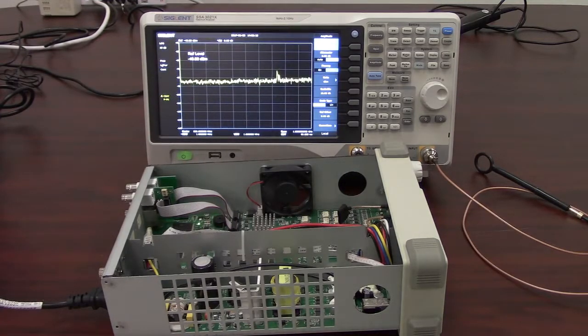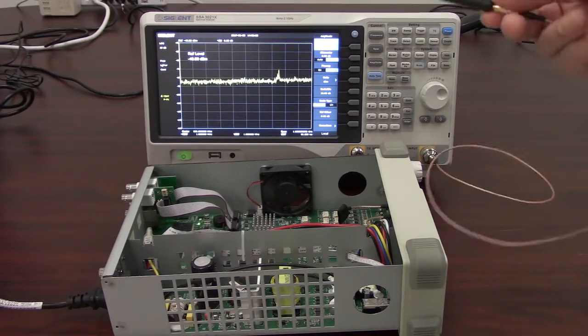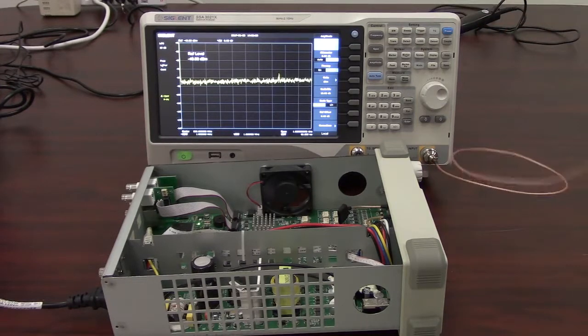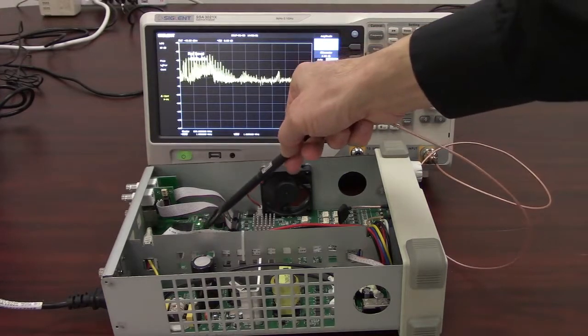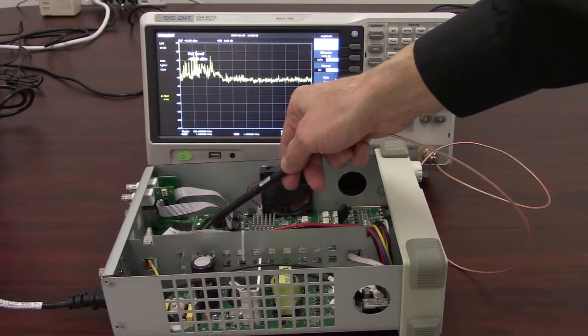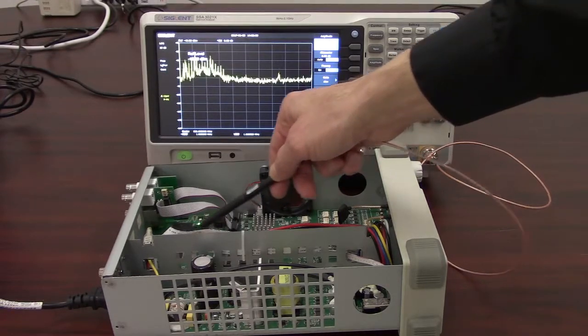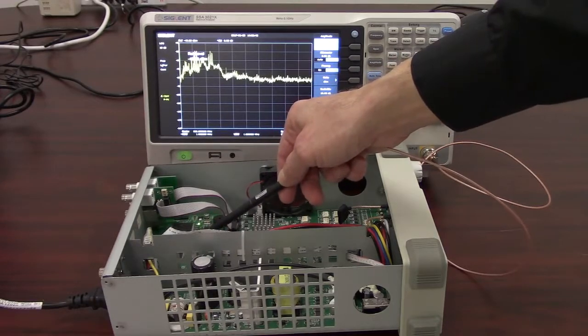And now let's take a closer look at an EMI application. In this case I have the SSA3000 or 3021X, and I'm going to be using a near field probe. This is a magnetic near field probe, the Siglent SRF 5030. And what you can do with a near field probe is, as you get closer to a source of radiation, you'll see the display start to get quite a bit of RF going on as we get closer to the DSP in this particular design.